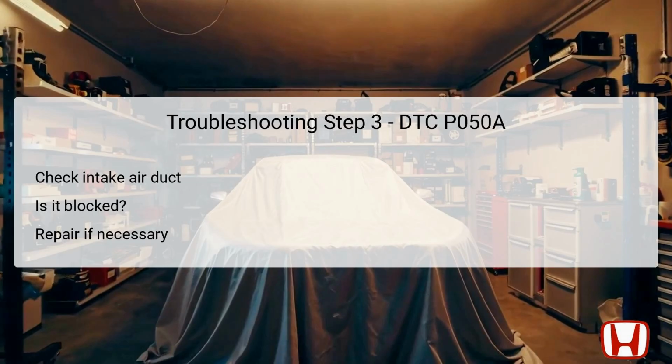Neglecting to address this issue could lead to continued performance problems and exacerbate the symptoms associated with DTC P050A. If the duct is in good condition, you then proceed with further troubleshooting steps to identify other potential causes.